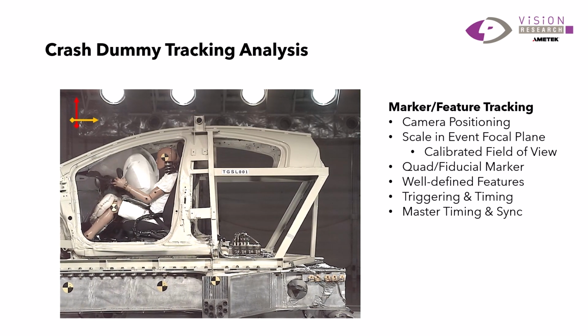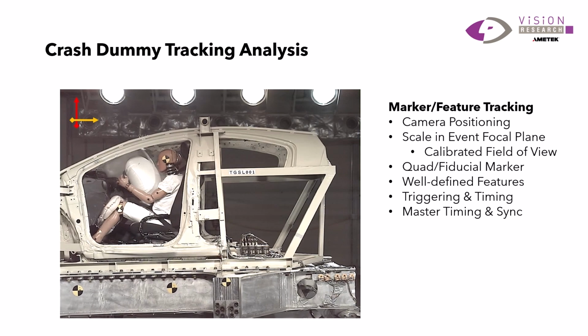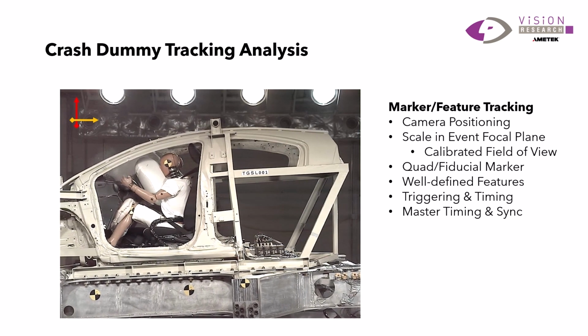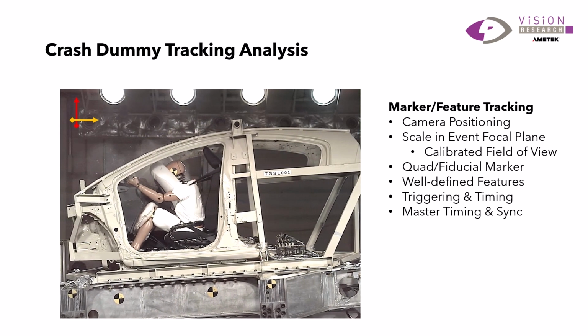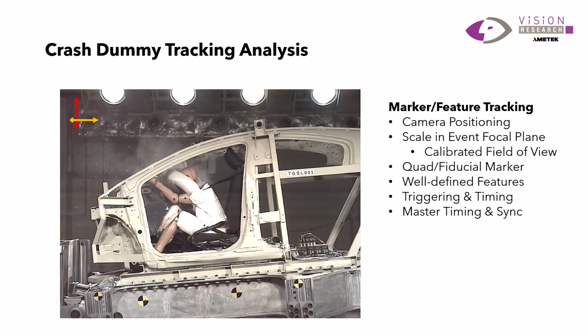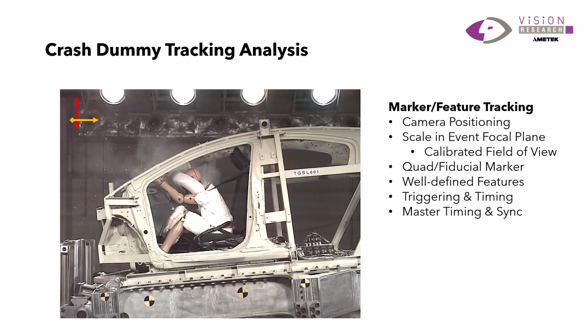Here we see the test proceeding. And what we don't see is that this test is very carefully timed, where the camera is synchronized with other data acquisition units. It's also triggered at a key moment in time relative to the event, and there's generally a master timing for the experiment where each device, camera, any kind of data collection is occurring at the same time.